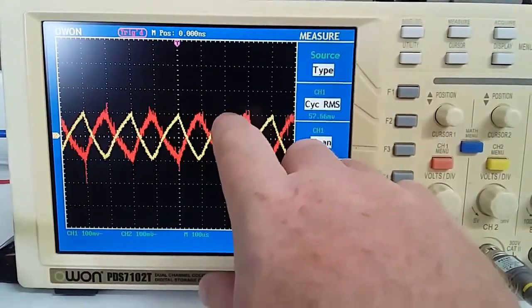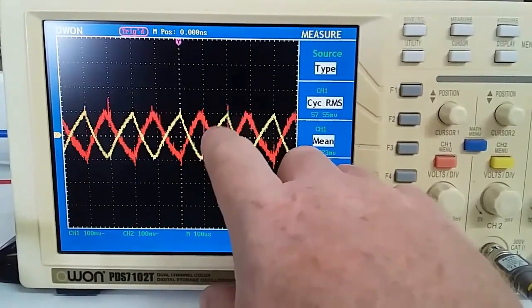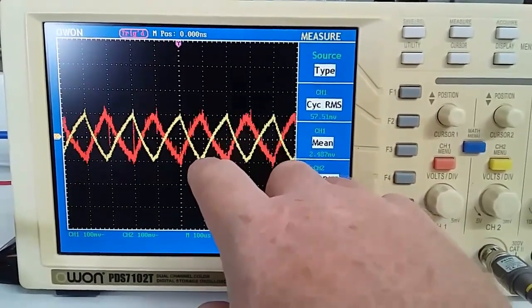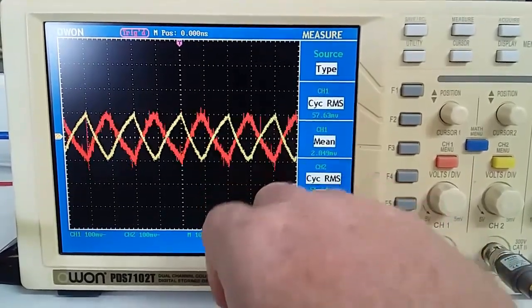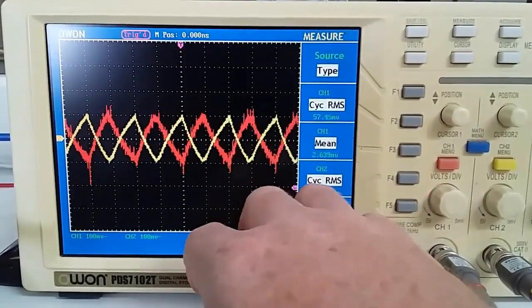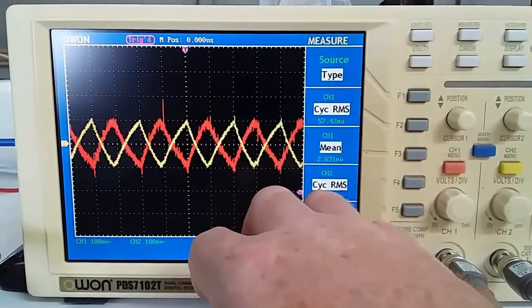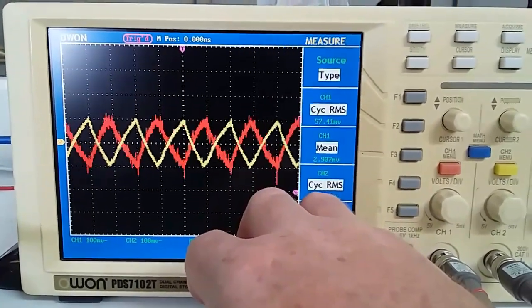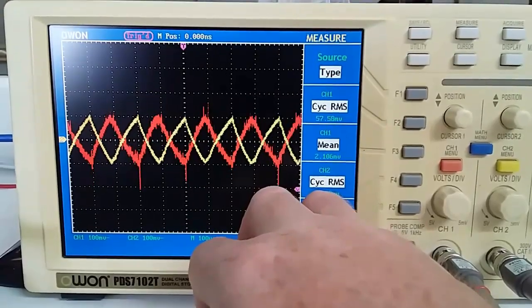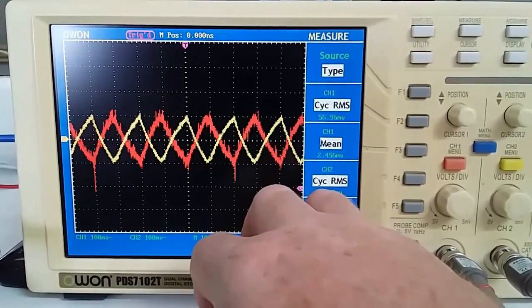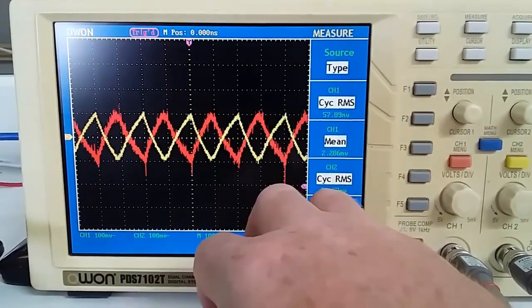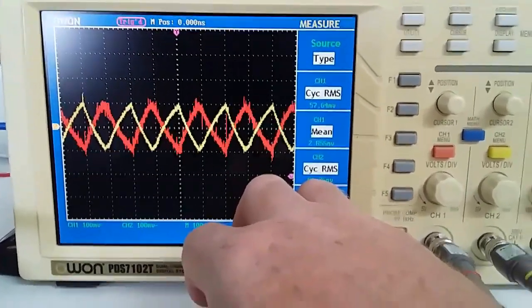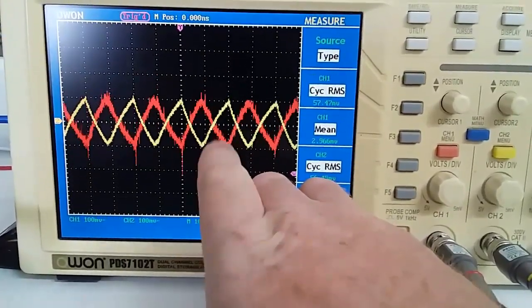It's not a linear process for the inductor to charge, so that's why we have a curvature there in the current. We've got to remember that coils and capacitors take time to ramp up and ramp down again. It's normally an exponential process as far as my simple mathematics is aware. So I just wanted to show you that.